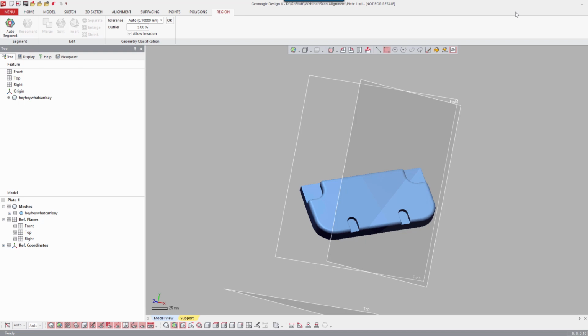If you've done an alignment later on, you'll know why, because if I start sketches and build things, and then align my mesh, the mesh moves and the other stuff stays behind. Everything I've built is no longer tied to my mesh. The mesh is what we use for all our references when building our parts. So when that reorients itself and all my sketches and features stay lost in space, it's almost like starting over again. It's really frustrating if you don't know that ahead of time. So that's why I thought it was important that you see this.